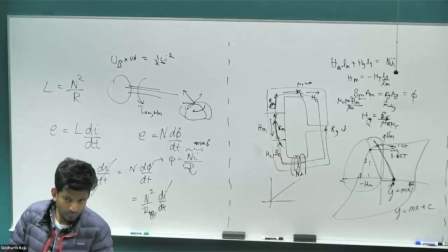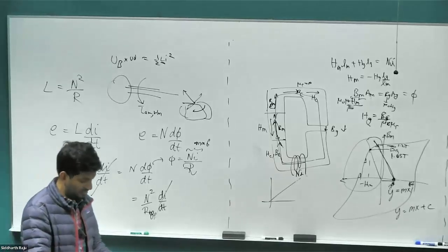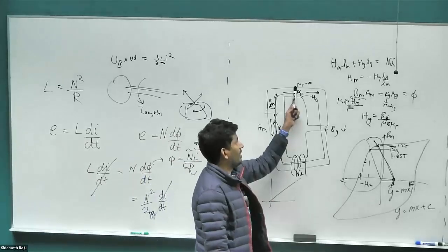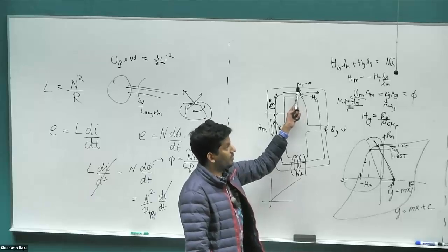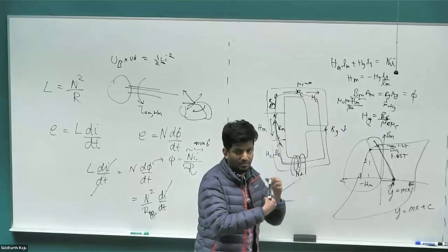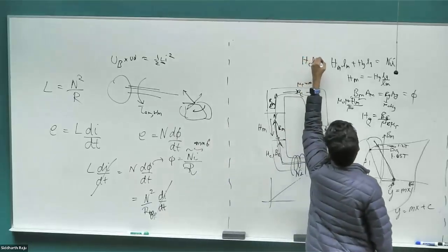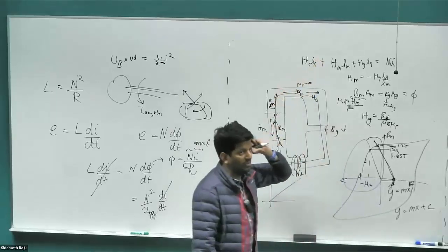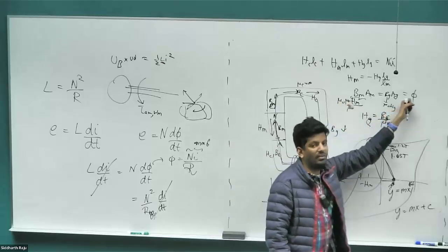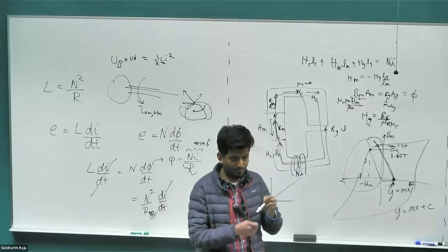Why don't you have to consider the core when you're adding the additional coil? Like why would you keep the relative permeability as infinite? If I give the relative permeability as infinite, then you can ignore it. If I don't give it, that will also get added. That will be a slightly more complicated H_c L_c. But it won't complicate it too much though, because H_c is again a function of flux divided by mu r times area.